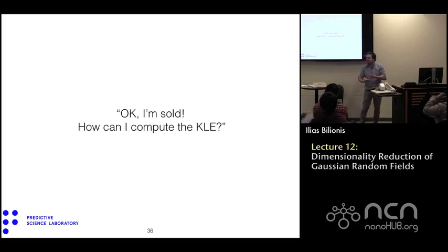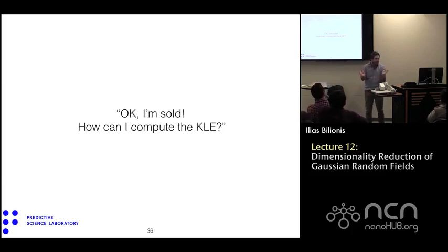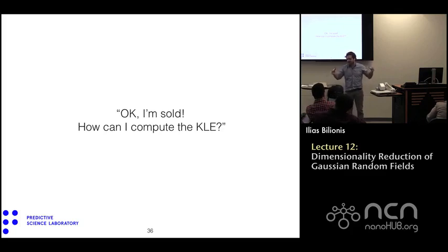So the important thing, which you need to know, the engineers in particular, is how to translate what you know to covariance functions. That's all, really. So it's extremely important to understand this connection more than it is to understand the math. I mean, you need to understand this connection, and then to understand that, you probably need to use a package that will turn this understanding into a finite dimensional description of the random field using the Karhunen-Loève expansion. It suffices to know the keywords because such codes do exist, okay? But garbage in, garbage out. So you need to understand the first part, which is the most important one.